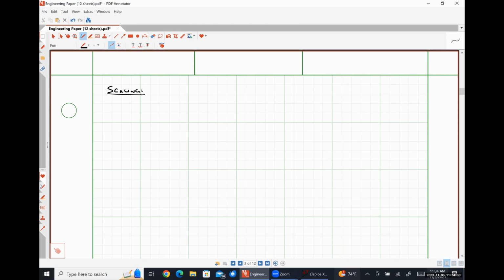In a lot of the examples that we've worked in this class, I've used ridiculously large values for capacitors, things like half a farad, mainly because it made the math easier to deal with. So now we're going to talk about how we scale circuits in order to actually use practical values.